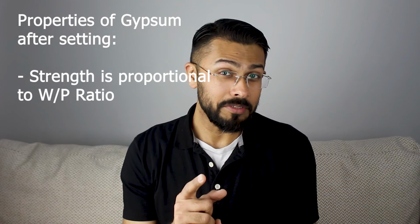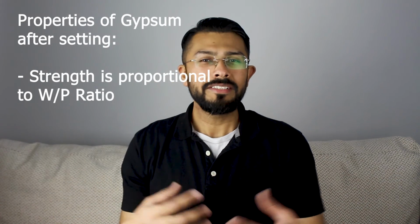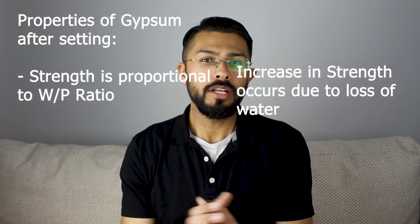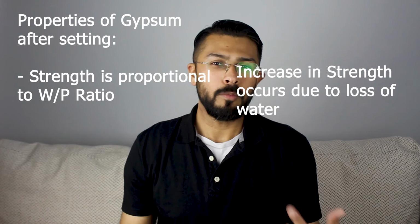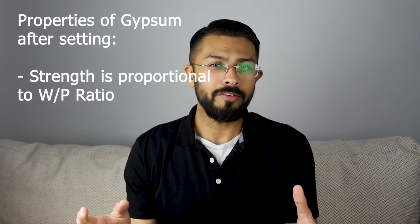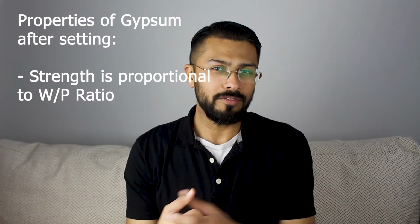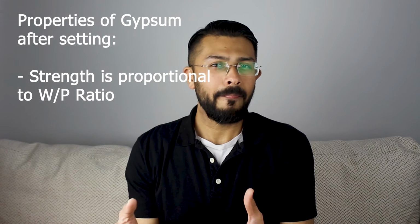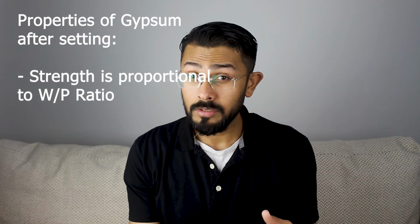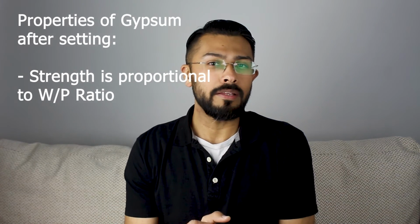Although a gypsum model or die may appear completely set within a relatively short period, its strength increases significantly if it is allowed to stand for a few hours. The increase in strength is a function of the loss of excess water by evaporation. It is thought that evaporation of water causes a precipitation of any dissolved dihydrate and that this effectively cements together the crystals of gypsum formed during setting. So, if you let your model or die dry out for a few hours before starting to work on it, you will have much better strength.